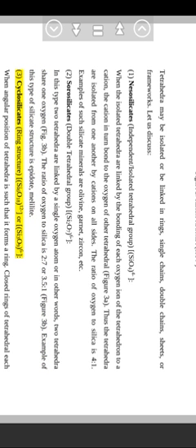3. Cyclosilicates, ring structure, Si6O18 12- or Si3O9 6-. When the angular position of tetrahedra is such that it forms a ring, closed rings of tetrahedra each share 2 oxygens, figure 3c. The ratio of oxygen to silica is 3:1. It forms the following 3 types of closed rings.